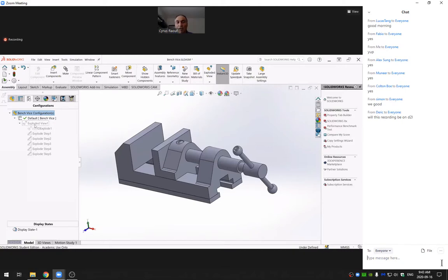Now, you can create more than one exploded view, and each time you say exploded view in the assembly environment, there will be another node, for example exploded view 2, exploded view 3. So be careful when you're creating an exploded view and you want to create only one. Every time you go there, you have to open this one, and from there you can edit the feature.